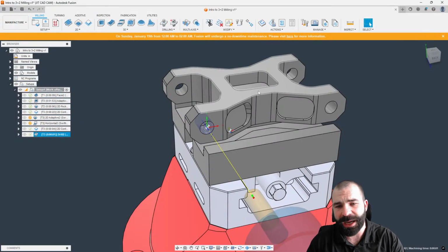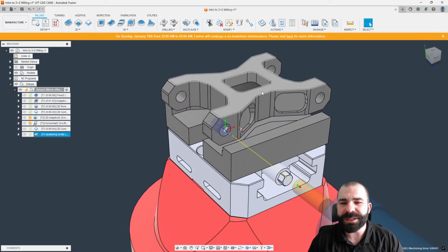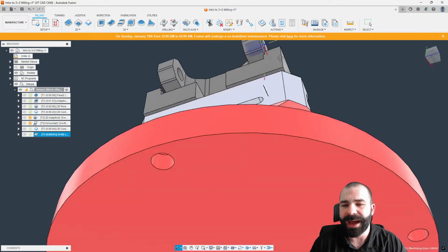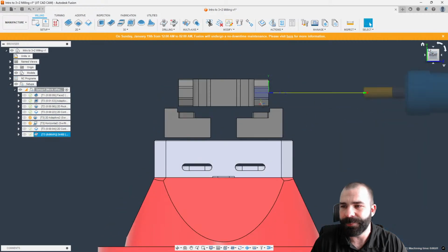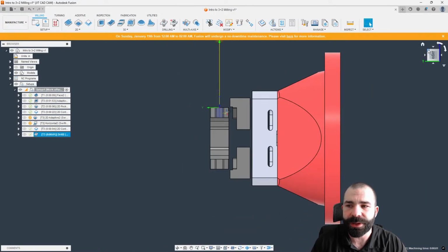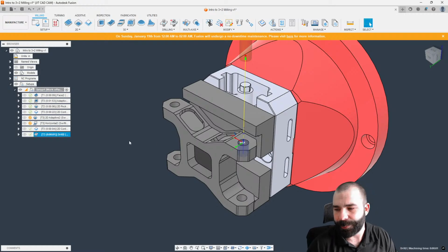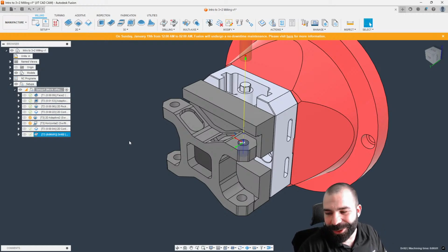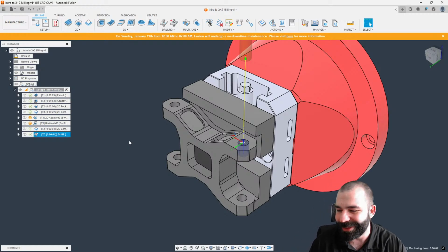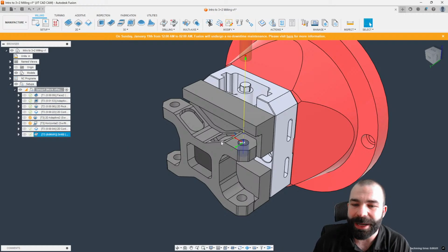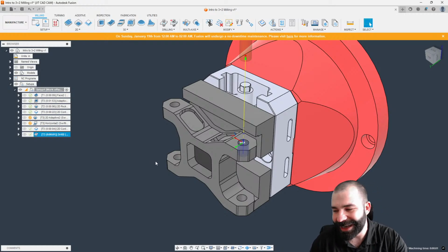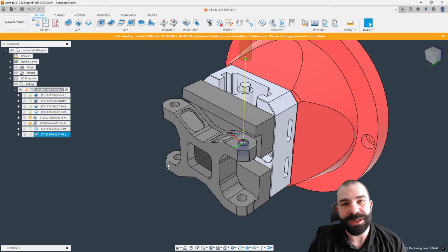And the same thing would be for you Haas guys and anybody else out there. So if you're somebody doing quite a bit of work in that mindset of fourth axis machining, right? Let's say, for example, this is sitting over to the right of our table. Again, we could actually place 2 or 3 joint origins to get to certain angles that we're going to consistently use on that part. So you guys let me know in chat. Did you guys know that you could use joint origins for that? It was something that one of my customers asked me if there was a way to always set a reference for tool orientation, so I didn't have to go through and select it a million times. But as you can see, it actually helps out a ton if you're going to be doing it more than once, of course.